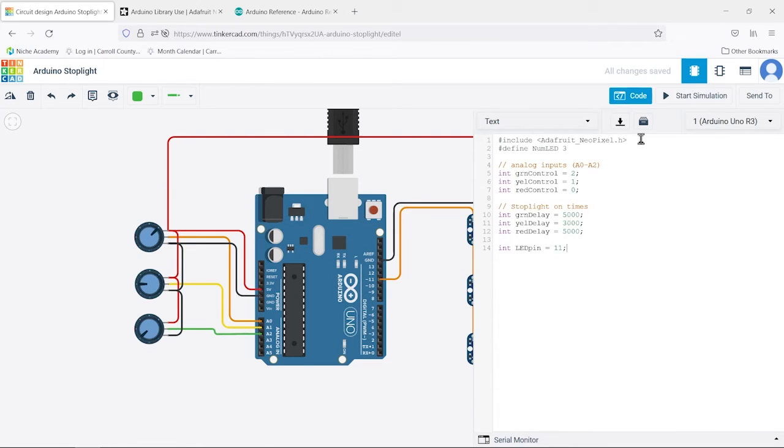The practice of using variable names in code as opposed to the explicit value means that should anything change, perhaps using more than 3 LEDs, or maybe having to use another pin assignment, all that needs to be done to update the code is to make one change to the variable declaration. Using variable names as opposed to numbers also makes the code more readable and easier to understand. It's easier to read red, yell, or GRN when addressing the specific LED than it is to remember which number they are in the chain.